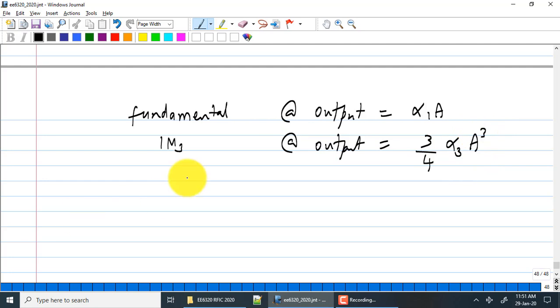Okay. So what I could say, now I'm going to call this amplitude as the A IIP3. This is the value of the amplitude corresponding to the input referred intercept point. The IIP3 is actually a power value. It is not an amplitude value. Because we are working with circuits, we have taken it referred to some amplitude.